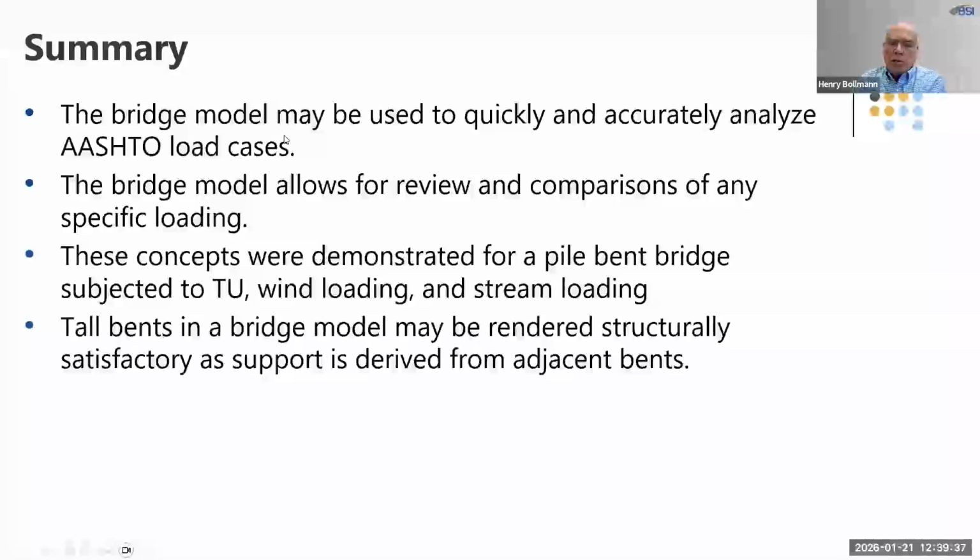So for the case of Pier 2, for instance, if you applied the 39 kips transversely from stream flow and only 20 of it went down to the soil, then the balance went up. If you went to a single pier model, you would be applying all of the stream flow of the 39 kips, but at the top on your bearings, you'd have a negative X force that you would apply at the bearings in the single pier model. And likewise, similar things for the others.